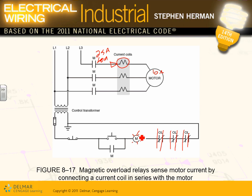Everybody knows how this system works, guys. When you push the button right in here, you energize this coil. These contacts, bam, bam, bam, will close. Now my motor is running, right? You wire these on the left. The voltage here could be 480, and this side transfers down to 120 volt. If Derek went and opened this contact, the stop, this is my stop, if you open the stop, it will de-energize the coil, which de-energizes the motor. That's my overload.